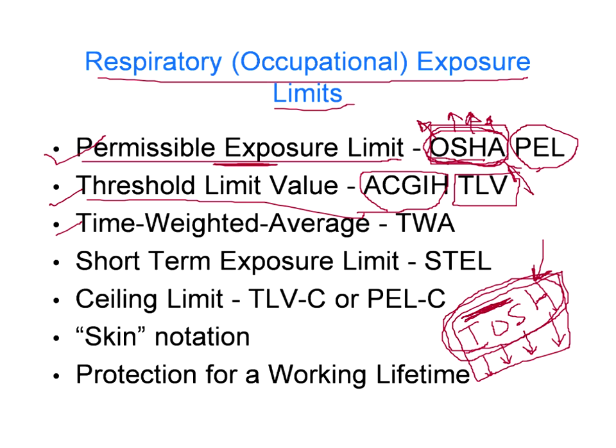Okay. So now we should know what the permissible exposure limit is. Permissible exposure limit means up to which point it is safe to allow a human being to work in an industry so that his breathing, or his respiratory system, is not affected. Okay, that is called PEL, permissible exposure limit.